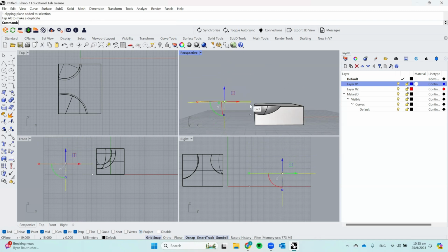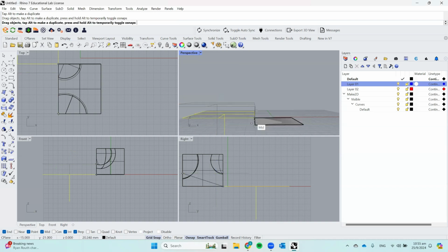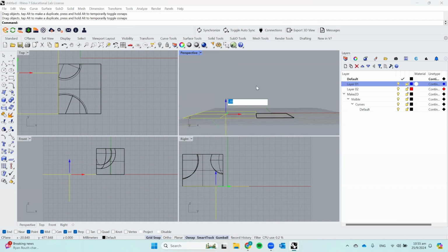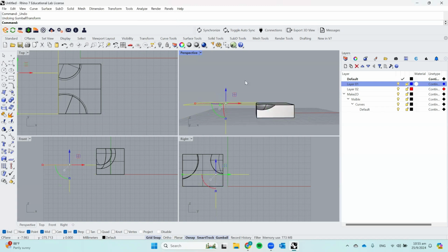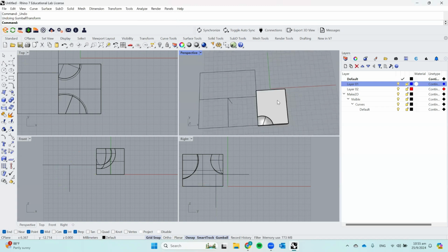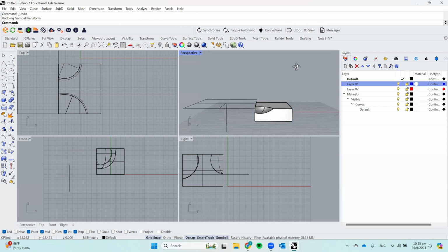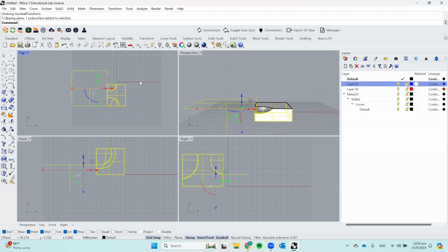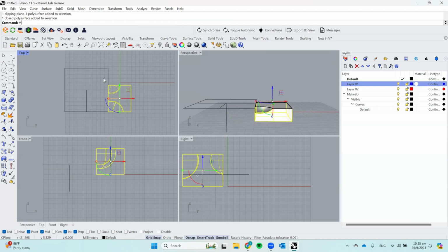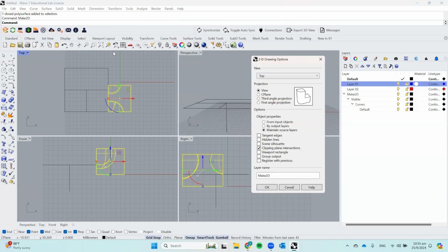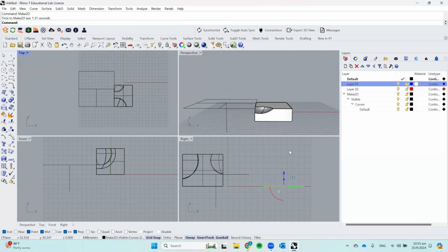So if I adjust this clipping plane to the bottom of my object, and then I increase it by 10 mm, essentially what I'm doing is I'm cutting this object 10 mm above the bottom. And then I can make 2D this view from the top view. So I go into top view and I make 2D. Right? So this is essentially I'm cutting a section.